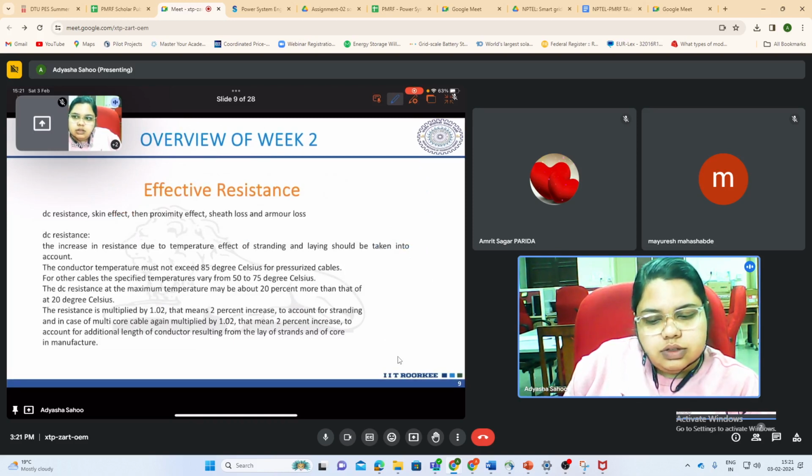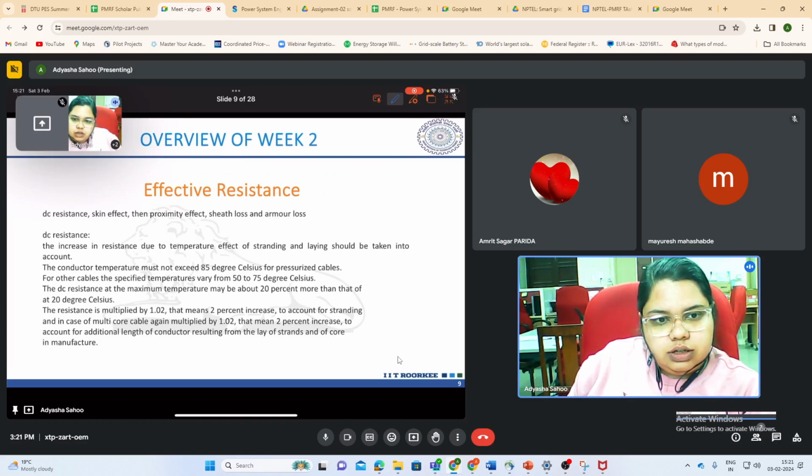Then the next thing that we studied was effective resistance. We are calculating the effective resistance of the cable considering various factors. And what were those factors? DC resistance, skin effect, proximity effect, sheath loss, and armor loss. So briefly, we'll discuss these one by one.